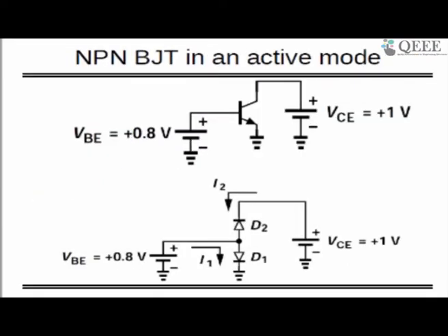So this is very clear that maybe you can mimic your circuit with two diodes D1 and D2. There is no problem, you can do that, but by putting D1 and D2 and mimicking the BJT, it's only on paper. In reality, to make this BJT, you need to make it an N plus PN structure, not a simple PN junction, PN junction.